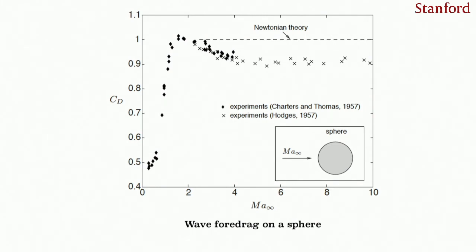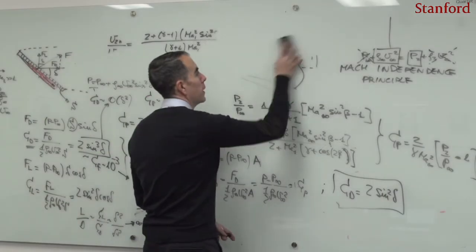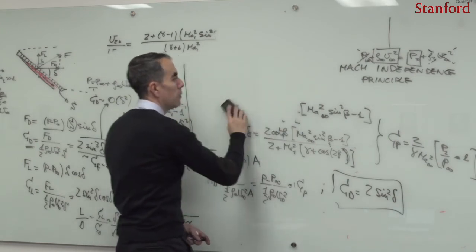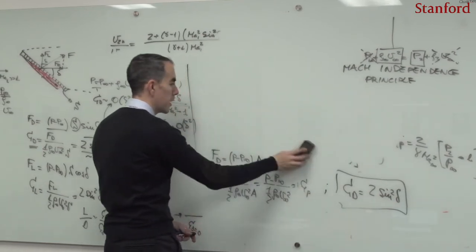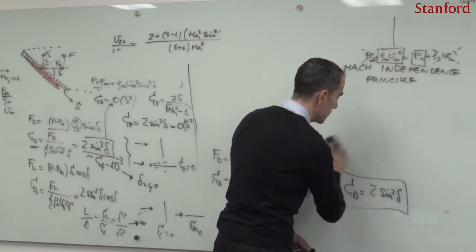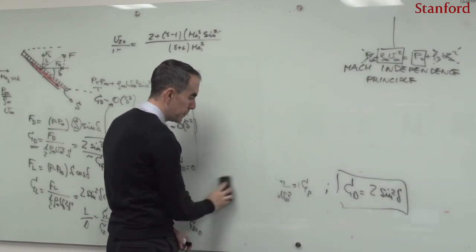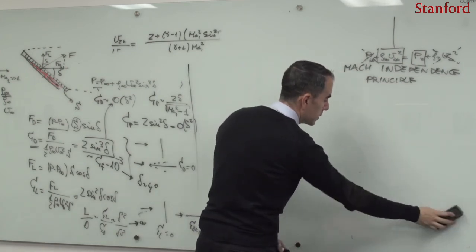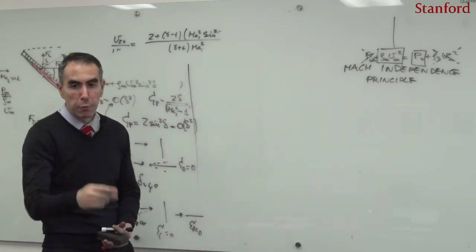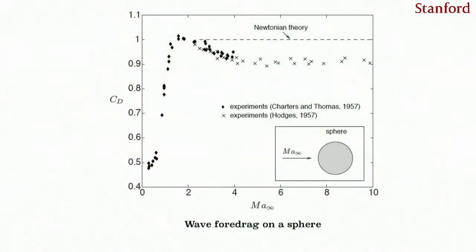Well, if we go back to this development, one of the problems discovered with the Newtonian theory, and it was discovered by Lester Lees in 1955, was that mismatch that you have just seen in the drag coefficient. Sorry, we go back to the chart. The Newtonian theory tends to overpredict the drag force by some amount, which is about 10%, right? So the question is, why is the Newtonian theory doing that? There was work by Lester Lees back in the 50s.